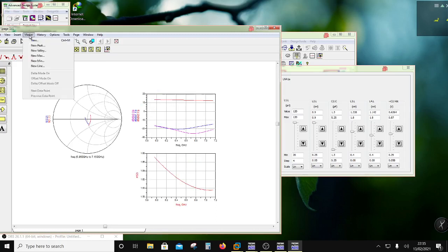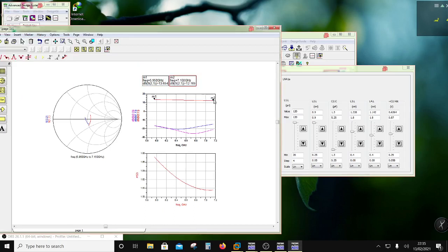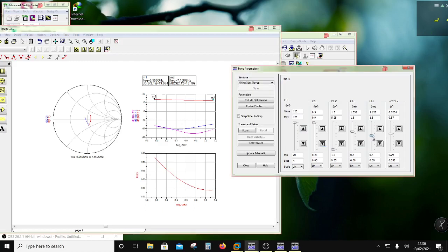And what happened to the gain droop? Because the gain droop is also important. This is 13.6 here and it is 12.1 here. So 1.4 dB is the variation, right? So now if I further reduce this, okay, so now I am going to just accept this as is, right?